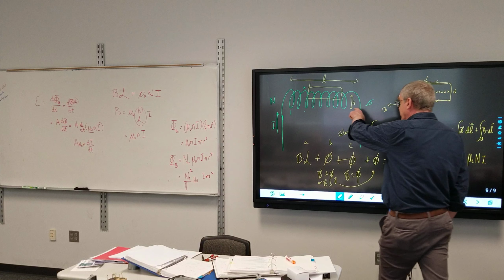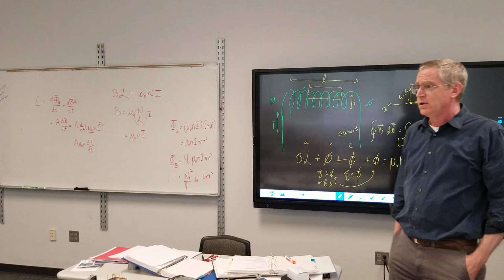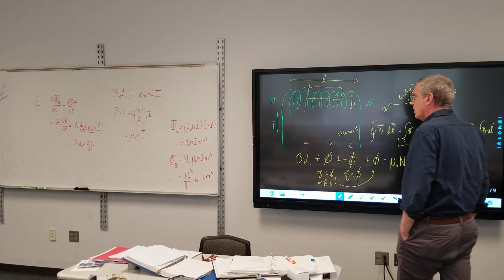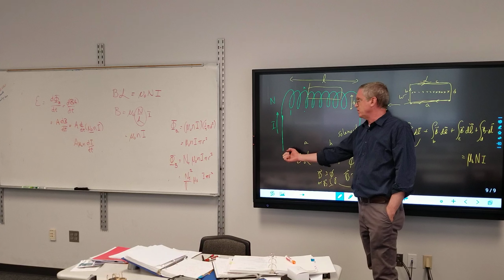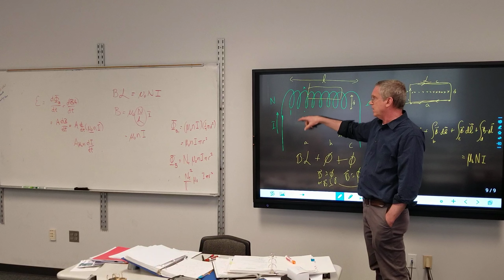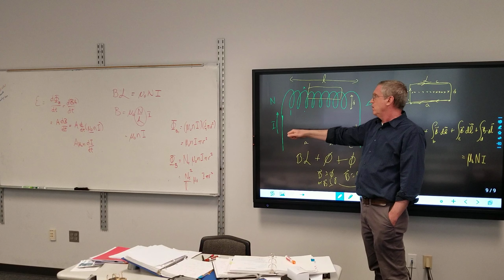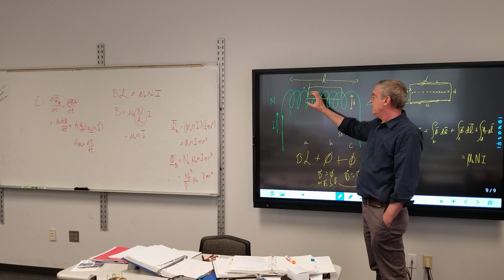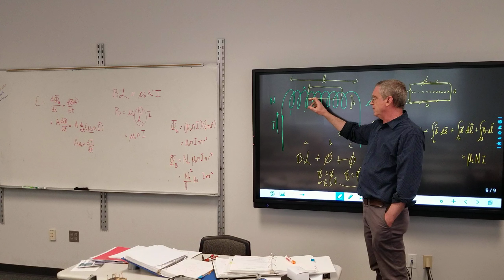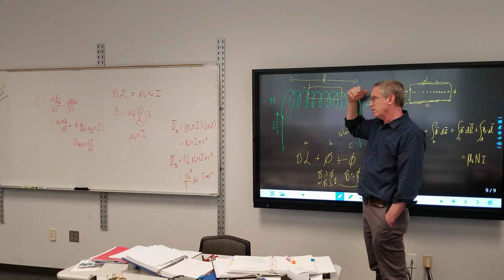Now, in the case of the solenoid just by itself, it does induce a current in itself. It wants to slow down, so as the current suddenly increases, it's going to create a secondary current in itself, which wants to slow down the increase in the magnetic flux. When you turn it off, it creates a secondary current in itself, which tries to boost up the collapsing magnetic field.